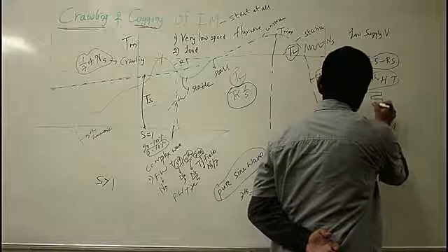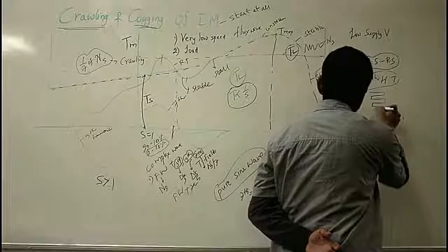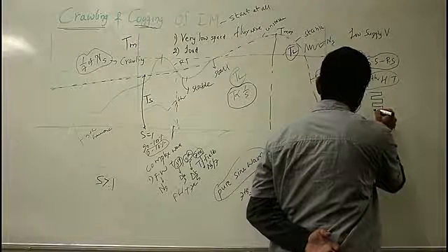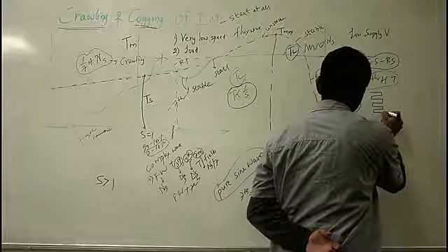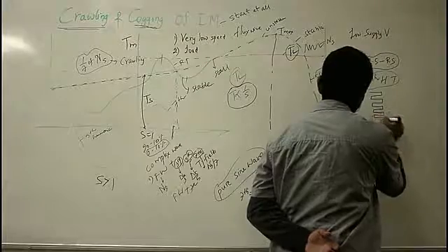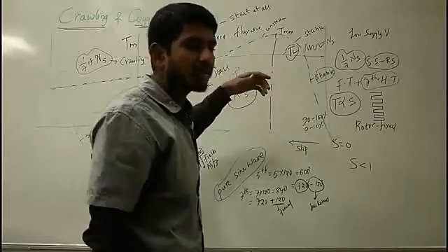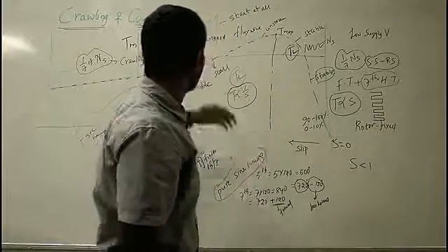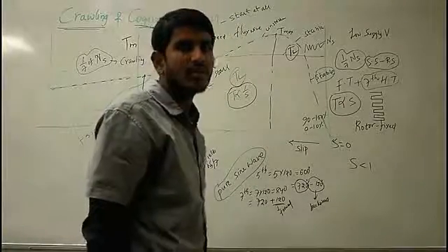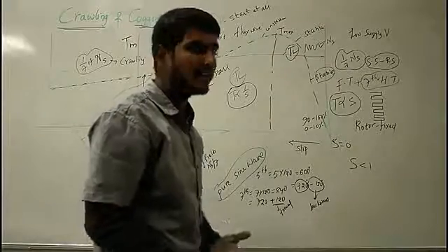and when they both face each other, at this stage the reluctance of the magnetic path is very low, or you can say minimum, and hence the rotor remains fixed and the motor refuses to start, and this characteristic is known as cogging of your induction motor. You can say magnetic teeth locking.